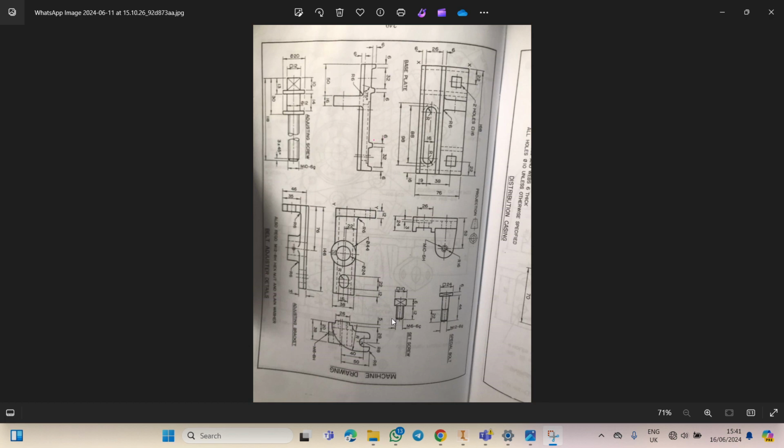So this video is going to be on the screws, threadings, and the holes. Like here, we can see they give a specific screw to use: set screw of M6 6G. Then here they give M12 6G, and it has to be in line with the holes. You can see this hole here, the hole was M10 6H. So you don't just create holes like that, you have to work with the specified hole or screw.